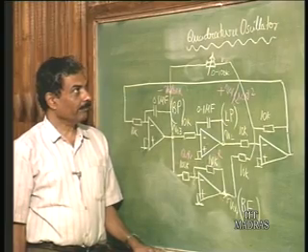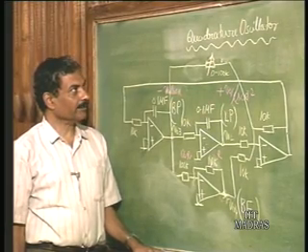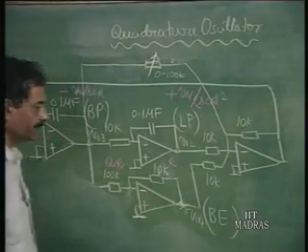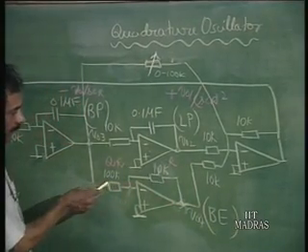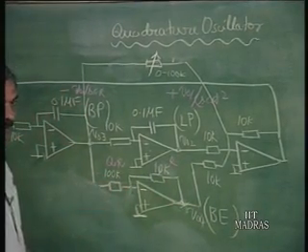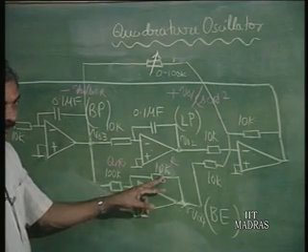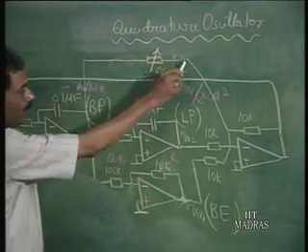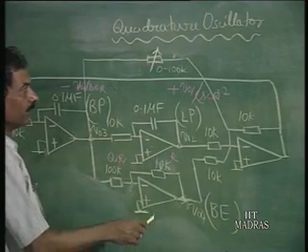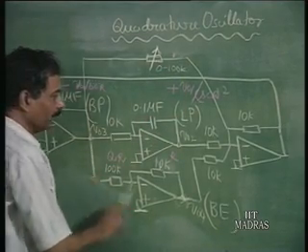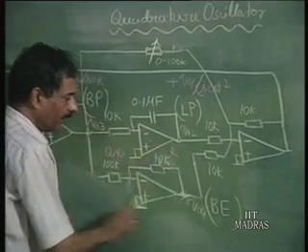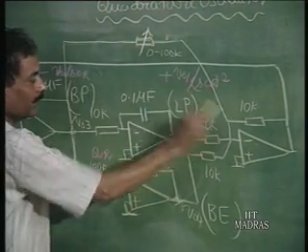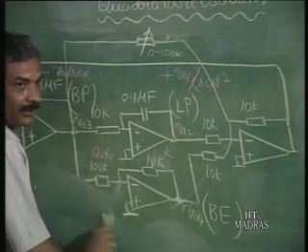Now, I am demonstrating another experiment using the same block. We had this part giving negative feedback, and Q here has been adjusted to be 10, brought back to 10 from 100, 10K, 100K. So, I put a 100K variable resistance here, so that Q can be made infinity. From here to here there is negative feedback if it is fed this way, but from this to this it is directly getting fed without going through the inverter.